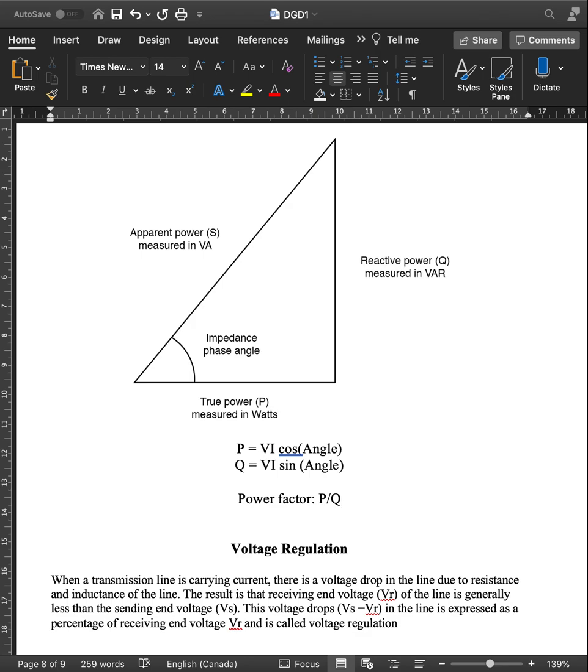Generally, when we have an AC motor of inductive type, it has a low lagging power factor between 0.1 and 0.3, extremely low, on a light load. However, when you increase your load, like on a full load, it generally goes to 0.8 to 0.9. So it's just a thing to keep in mind: when you have a load, the power factor would be around 0.8 to 0.9 or between them. It's never higher or lower than that.